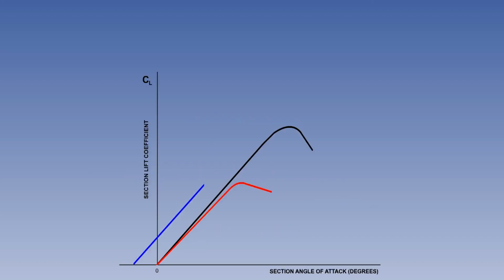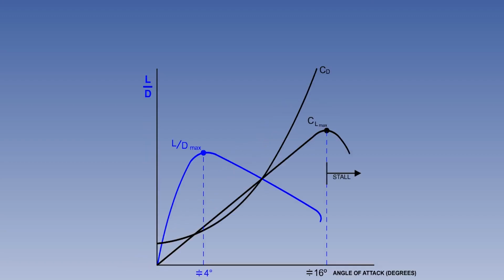The lift curve can be used to gain useful information about an aerofoil's characteristics, and, when used in conjunction with the lift formula, can give further useful data. The lift curve will be seen again soon in the lift lesson, but in combination with its counterpart, the drag curve. As you will see, drag is inseparable from lift.